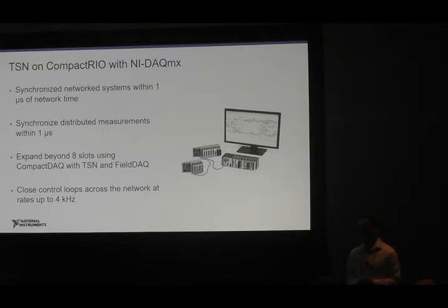And specifically one thing I said I was going to come back to is an additional expansion option, which is, now that we support DAQmx on these products, we actually have support for CompactDAQ chassis. Specifically, the ones I want to call out are CompactDAQ with TSN chassis. So from a product perspective, this is cDAQ-9185 and 9189, so 4 and 8 slot devices that you see up here. And they do support TSN, so the synchronization aspect of TSN and being able to synchronize data. So there are a lot of applications that are out there where 8 slots of I/O just isn't quite enough. And this is where TSN really comes into play.